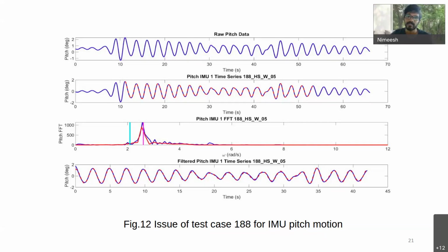Since you precisely know the wavelength of the wave, and you know the reflection will come back in so and so time, based on the fact that you have 30 meters of wave basin length. It's a little more than 30 meters because we may be 10 meters away from the wave maker. So we have 20 meters for it to go to the beach and another 20 meters to come back. Correct. So we just calculate that time. For a conservative estimate, you may even choose 30 meters rather than 40 meters as the distance it needs to cover.